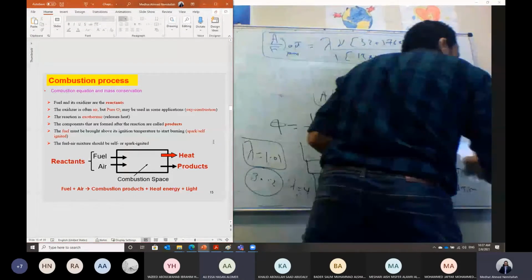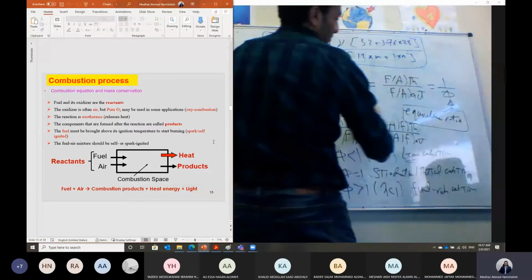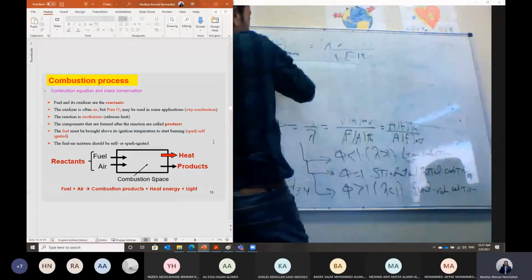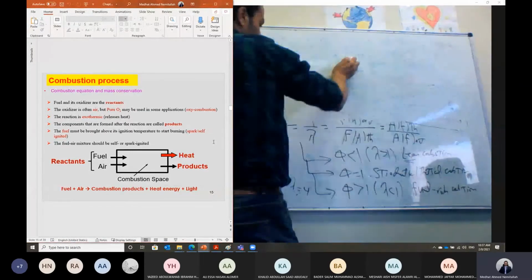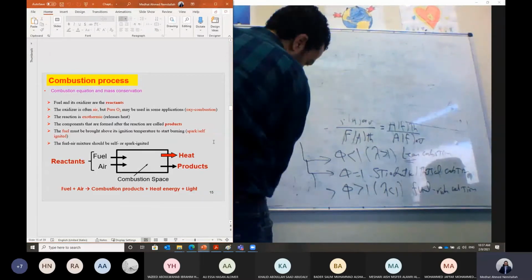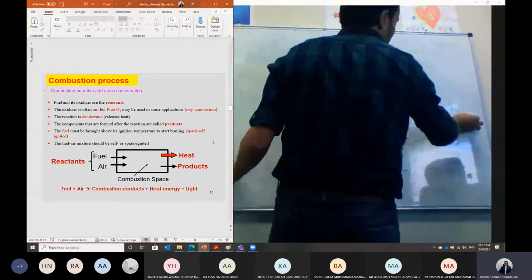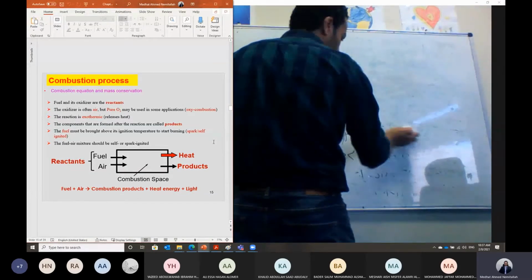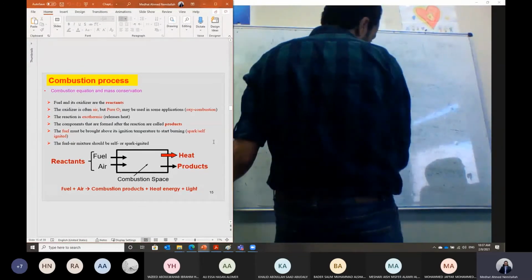This is good, okay. So this is how to calculate the air to fuel ratio. Usually we don't represent it in terms of air to fuel ratio. We represent it in terms of actual air to fuel divided by theoretical air to fuel, which can be represented either by the excess air factor lambda or by the equivalence ratio, which is 1 over lambda. So this parameter phi gives us an indication about the quality of the mixture, the ratio between air and fuel for a given mixture. As I told you, a gasoline engine usually works slightly lean, but in the case of